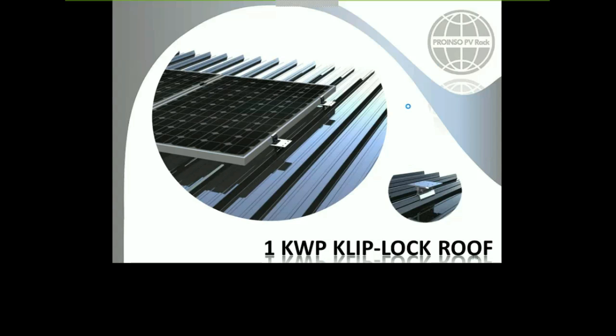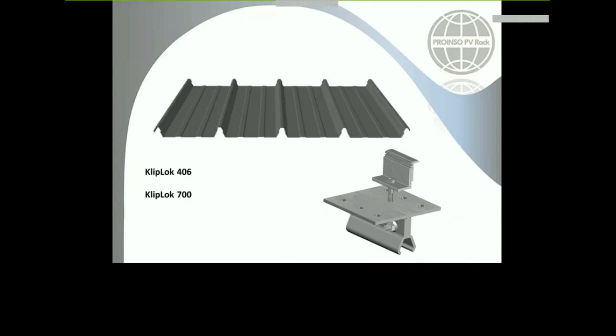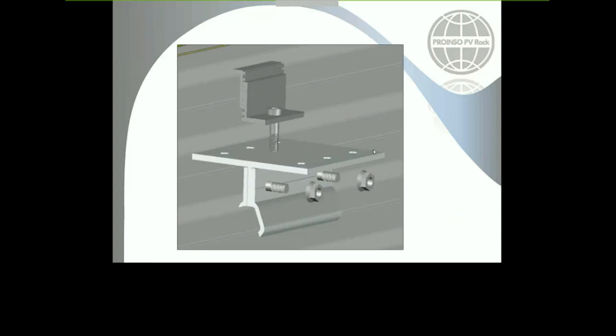The clip lock, as well, is one of the most simple ones. You just have the head of the clip lock shape. These plates come in two different ways, so you have to go to the metal roof, take one of the plates already fixed with the screw, the other one just slide it in here, adapt to the head, and tighten it. Okay, in this case as well, you have to ensure the alignment between one to each other, okay,